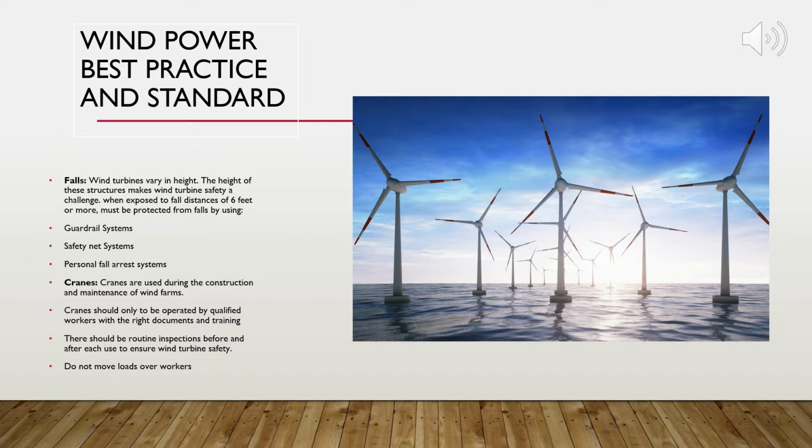Cranes are used during the construction and maintenance of wind farms. Cranes should only be operated by qualified workers with the right documents and training. There should be routine inspections before and after it is used to ensure wind turbine safety. Do not move loads over workers.